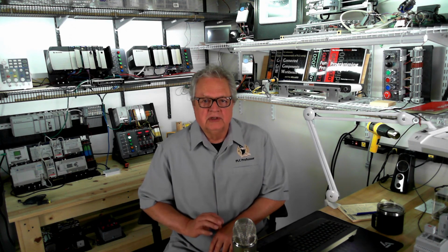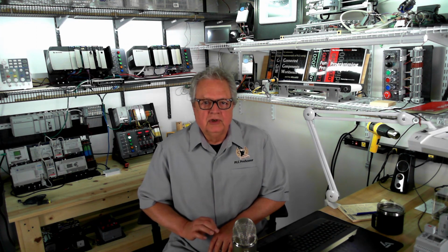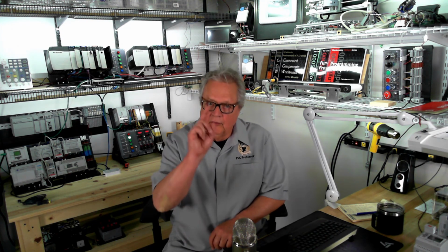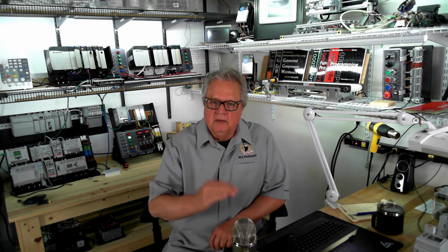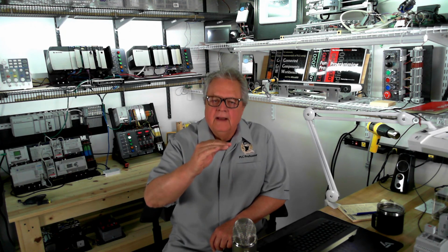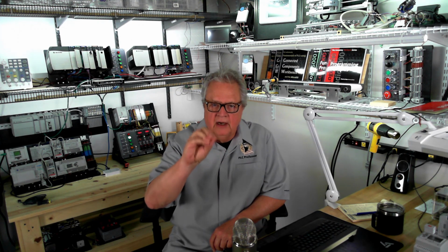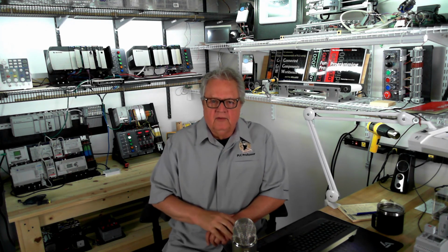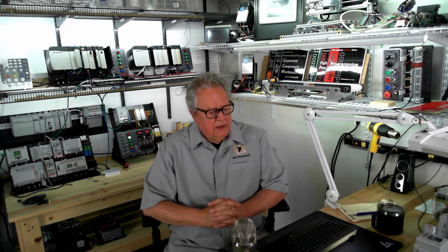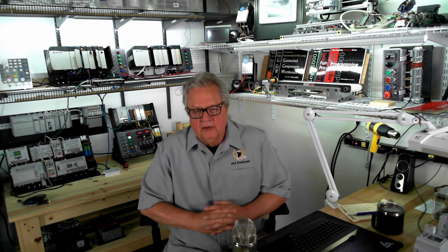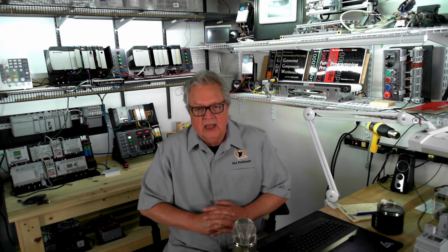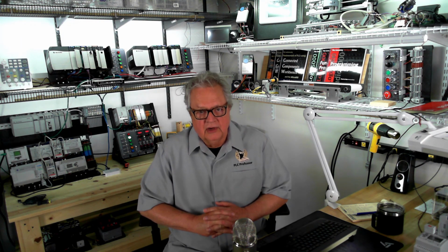When those cases come up, you want to make sure that you put all of that logic that's scan dependent into one rung. That way, if the rung gets moved around, it's not going to hurt anything because the scan dependency is embedded in that one rung. That's a subject for another lab project. So that's what you should walk away with from this lab project, is the relationship between multiple rungs of logic and the bits in memory that they address.